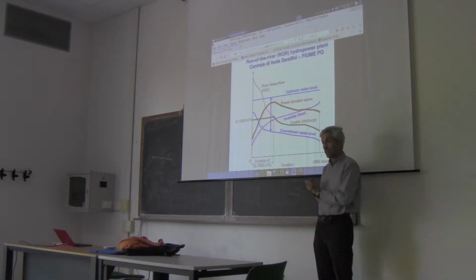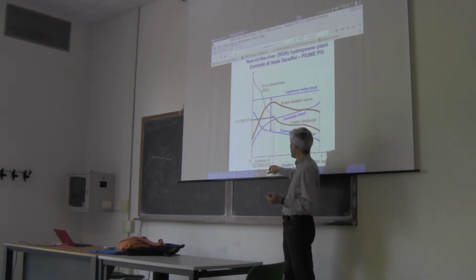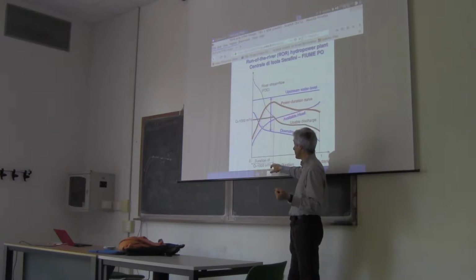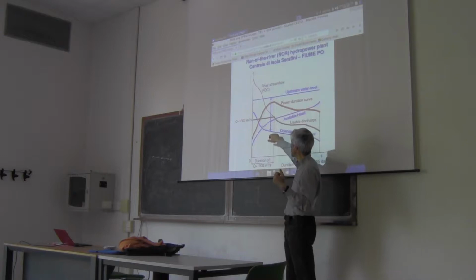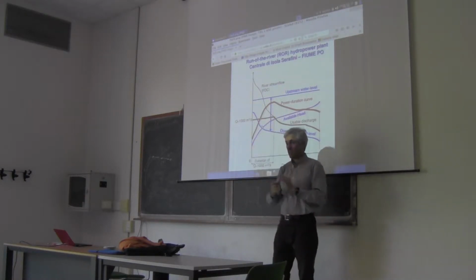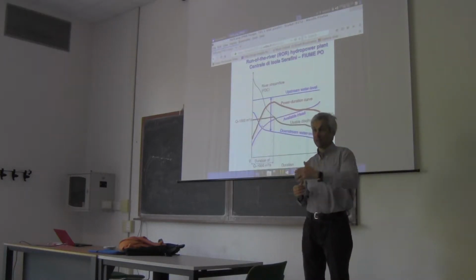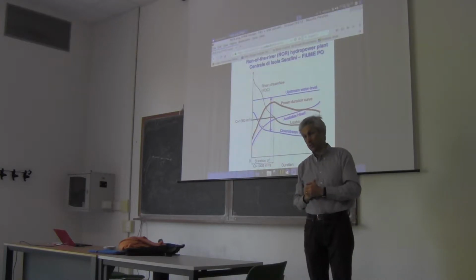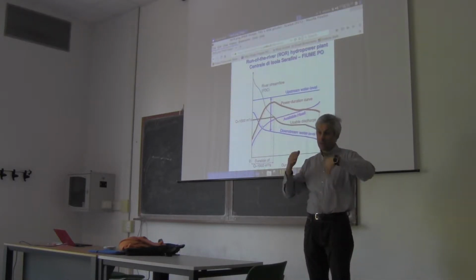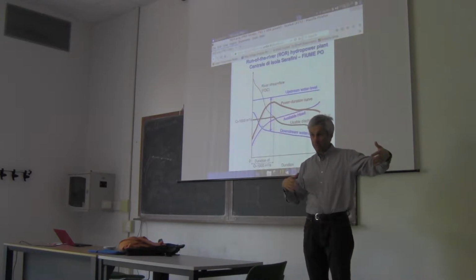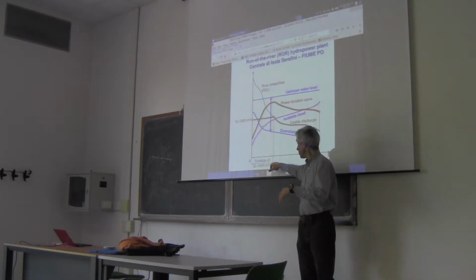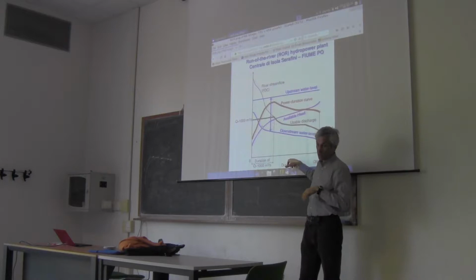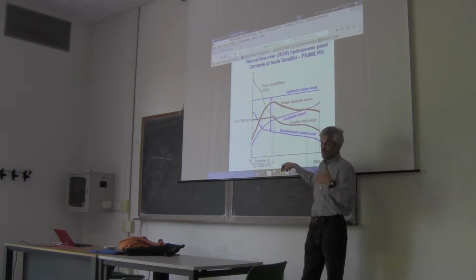So this means that with a river flow of 1000 cubic meters per second, I have the highest potential hydropower production, because the plant is working at full regime, at its full capacity, and the head is decreasing for increasing duration.